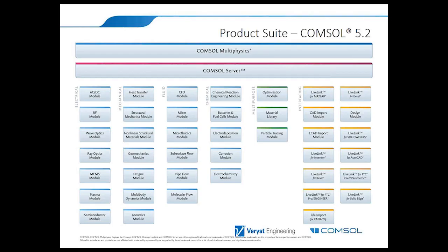And in many cases, we request additional testing to evaluate material properties that may be relevant to the accuracy of the model. Before requesting that, we can look at the sensitivity analysis to see if you change the material property within reasonable range, is it going to make a difference or not? So we're not just doing experiments for the sake of experiments. So that's how we do it.